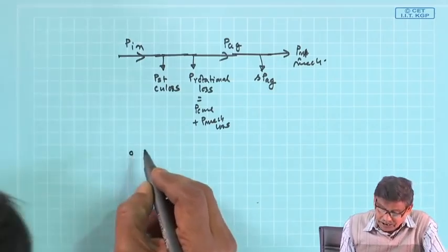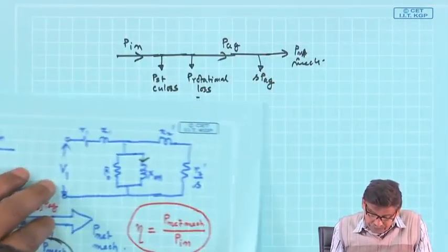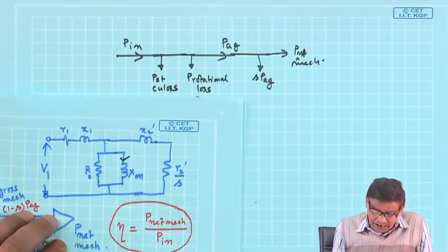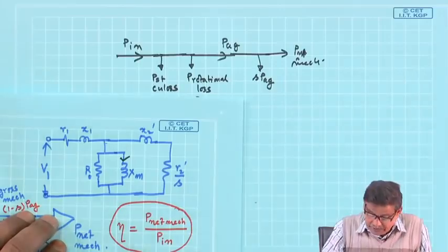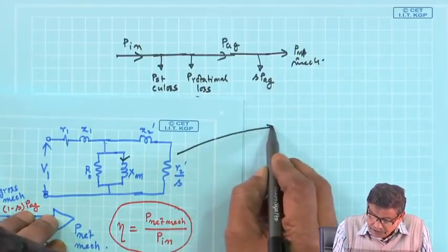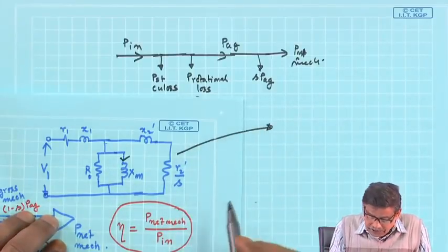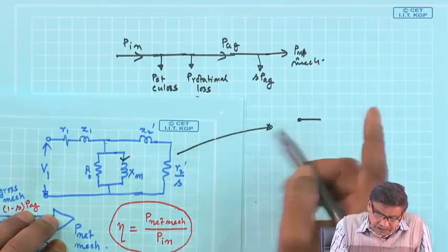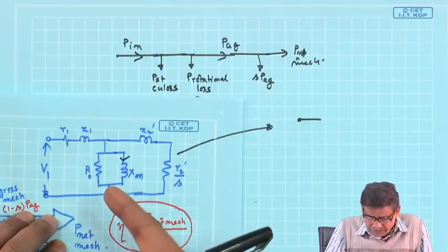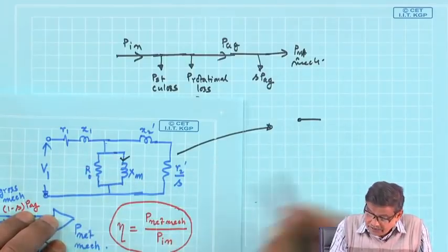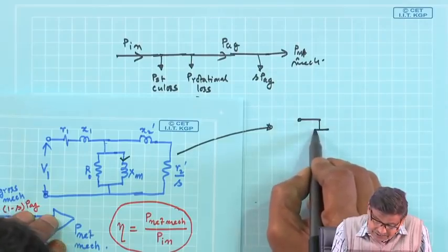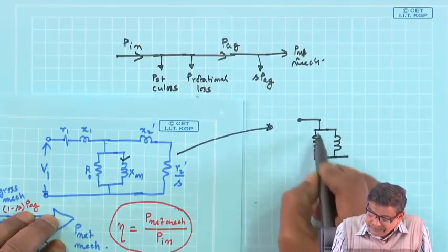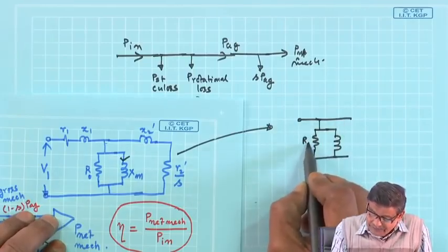So, this was the original equivalent circuit, is it not? Now, in this circle diagram, what further assumption will I make in this equivalent circuit? I will pretend like a transformer, with the plea that R1 X1 is smaller compared to R0 X0, I will bring this here, R0 Xm.